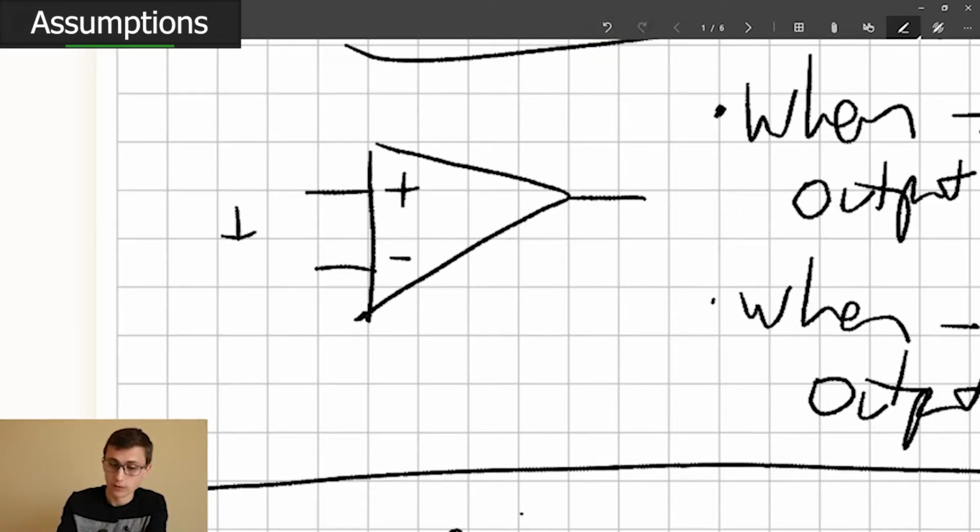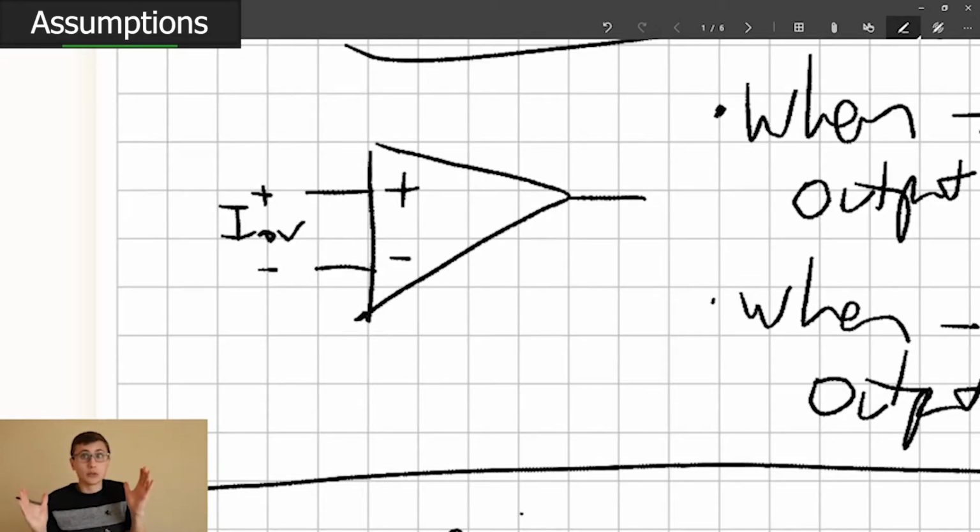We're also going to assume that there is no input offset voltage. Normally it would trigger right at that level, right? Say you've got 2.4 volts as the threshold and something slowly coming up, and you'd expect right at that threshold it would go kapling. Realistically, it probably needs to exceed that threshold by a couple millivolts. Perhaps there's some built-in hysteresis. Perhaps there's not. Could have some oscillation. Could be a little ugly. So we're just going to assume there's no oscillation and there's no input offset voltage.